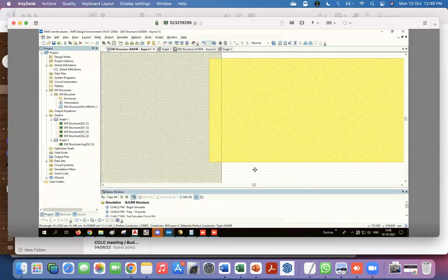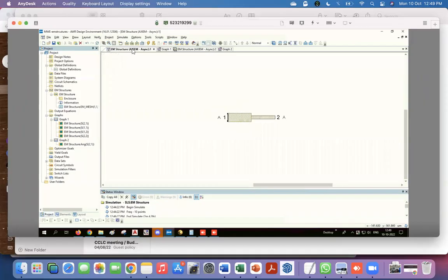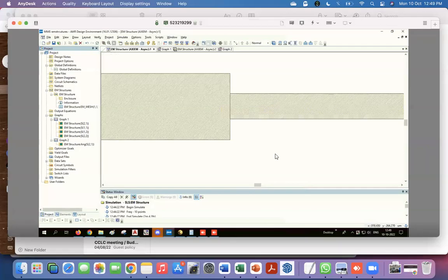This is also okay, but now the effective length is going to be on the edge here. It will not complain, because it's not like one going on top of each other. So you just have to make sure that they are in contact, and this can be a tricky thing, that if you are zoomed out, you might not be able to see whether they're actually in touch or not. So the reason for drawing this is to look at how the meshing changes.